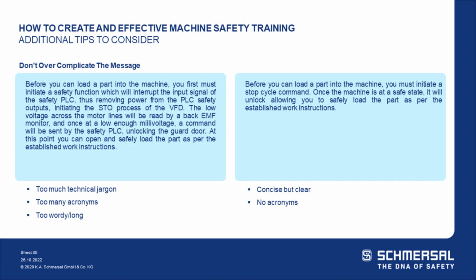If we look at an example of fine tuning that overall message, what I'm trying to say is, before you can load a part into the machine, you must initiate a stop cycle command. Then once the machine is at a safe state, it will unlock, allowing you to safely load a part as per the established work instructions.